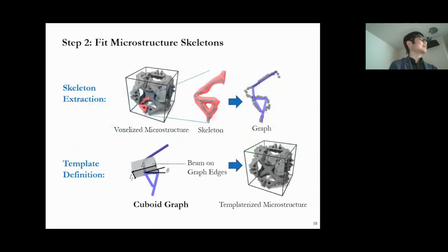And in this space, we further extract the information from the Eulerian representation that is on voxels to a Lagrangian representation based on graphs or based on connectivities and particles. Then we can parameterize each family of microstructure by way fewer number of parameters. For example, here we convert from a 64 cubed voxel space to maybe a 20-dimensional parameter space.